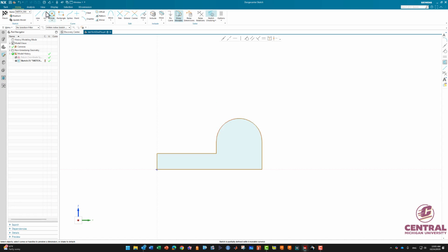So if you didn't activate any sketch tool, if you grab it, then you can actually move it. So you can show the degrees of freedom you have in your sketch on the element you grabbed. We want to have the exact size we want. To have the size, all you've got to do is click the line you want to have a dimension on. Then it will confirm whether you mean to click the axis or the line. The quick pick window will show up. Sometimes not, sometimes yes. In this case, yes. So I'm going to pick the line.